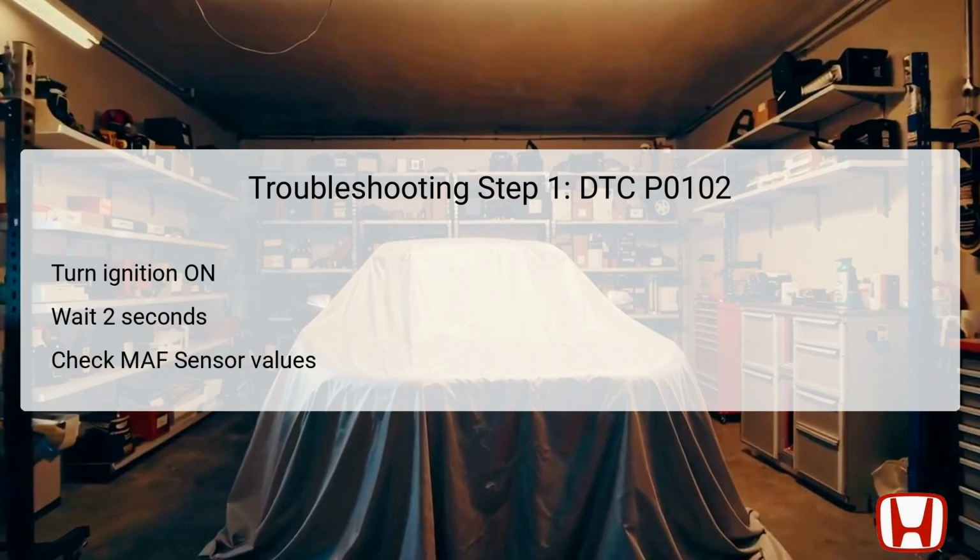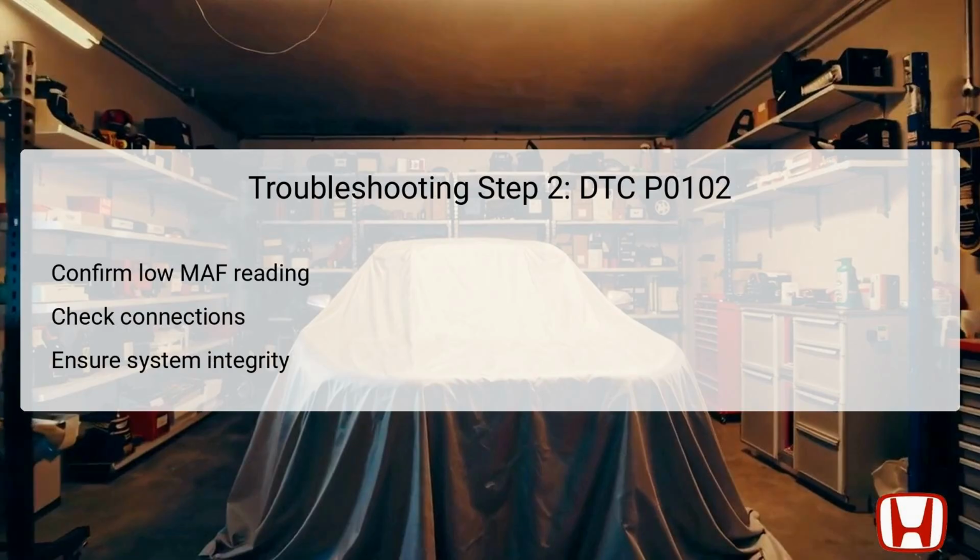After confirming a low reading from the MAF sensor, the next step is to ensure that the connections are intact and secure. Turn the ignition switch to the lock position and then disconnect the MAF/IAT sensor 5P connector. With the connector detached, turn the ignition switch back to the on position.